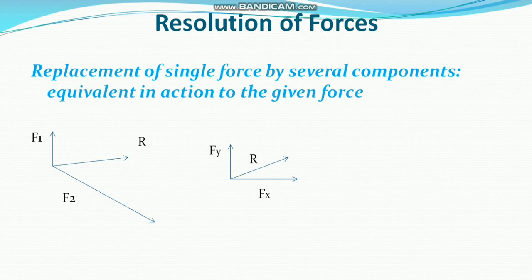Fx and Fy are mutually perpendicular and their resultant will be R. To convert from R to Fx or Fy is very easy. That's why we mostly use this resolution into two components, Fx and Fy. Or in other words, R can be resolved into forces F1 and F2, which are mutually perpendicular for our convenience.